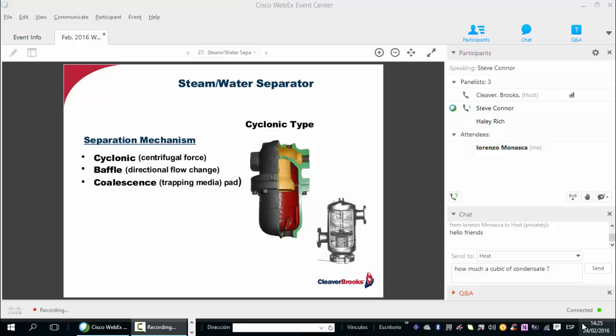You see, it really all starts with what I mentioned back in November, providing the driest, liquid-free steam to the user as we possibly can. And that many times involves the use of a steam separator, which separates the entrained water droplets using 3 optional methods, as you see on the screen, and then sending them to the condensate return line.